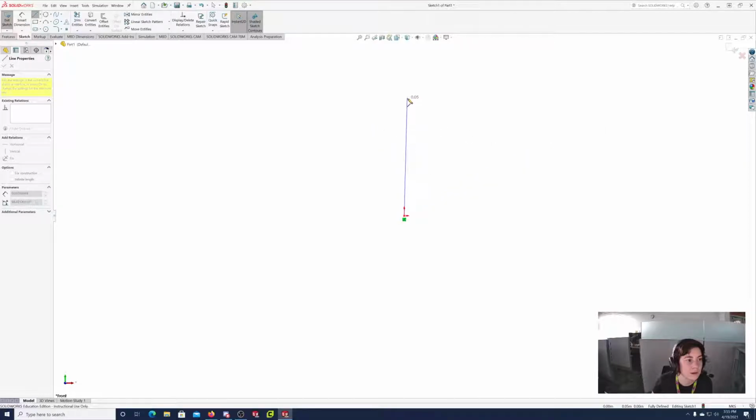And then you're going to just do a single left click again to release the end of the line wherever you want it. So that's one way to draw a line. The other way is to click and hold the mouse. So if I start at the origin and I click and hold down my left button as I drag the line, and if I release it, it will just release the line wherever I left it.